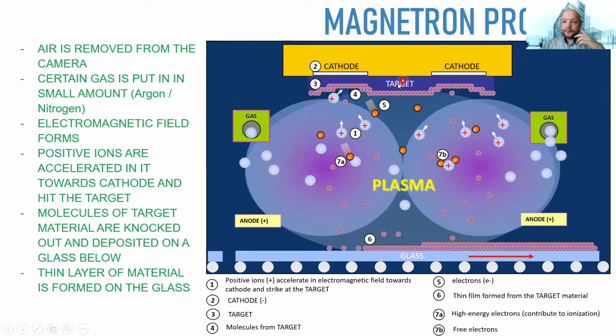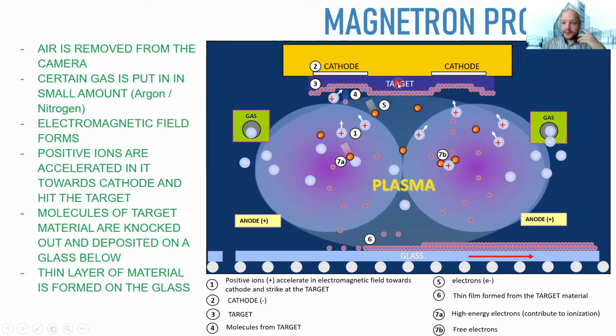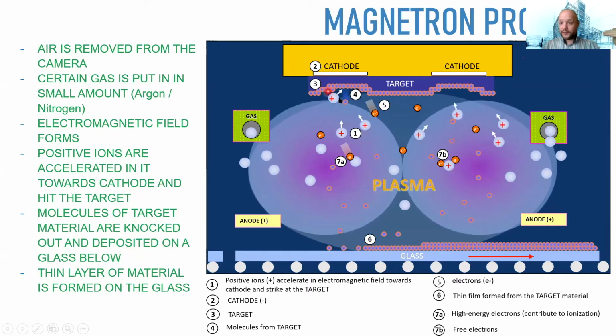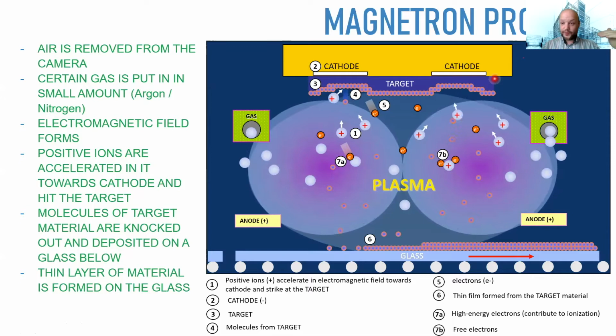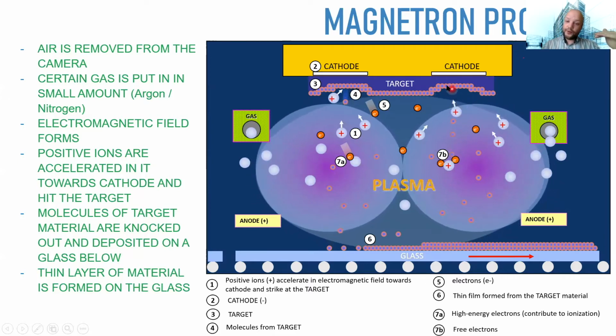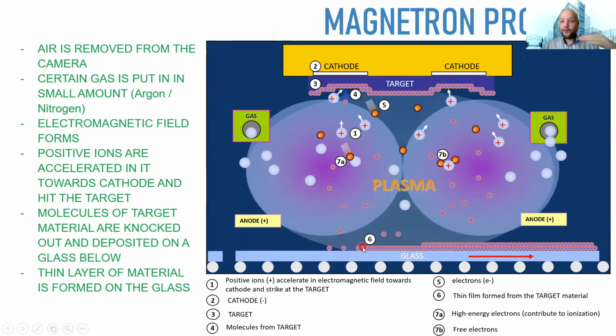For example, in all glass having low E properties made with the magnetron process, the key material is silver. So here you have a target weighing 20 plus kilos of silver with the purity of 99.99%, so very pure. You put argon gas there. Argon is not chemically reacting with anything. So it is bombarding and dropping, and pure silver is dropping on the glass, forming a silver layer.